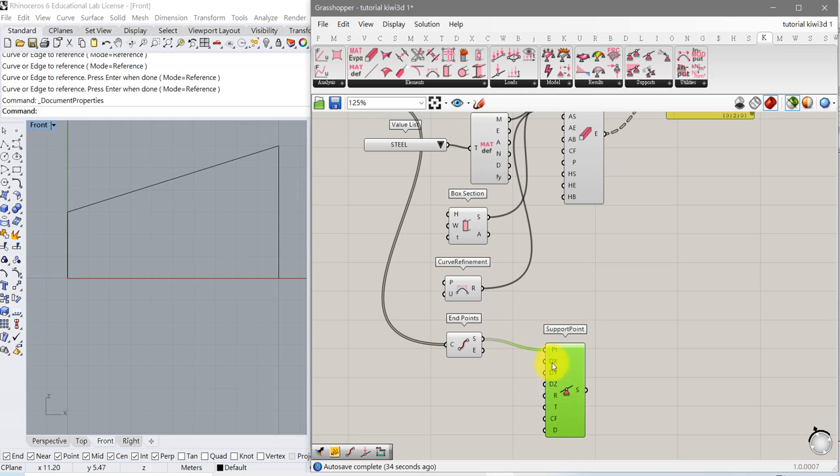I think by default they are all true. And for rotation, the default value is false. So by default it is a rotatable supporting point, and T means torsion. So it also allows twisting, which means the support will not resist twisting. This is for more advanced use. We skip it.